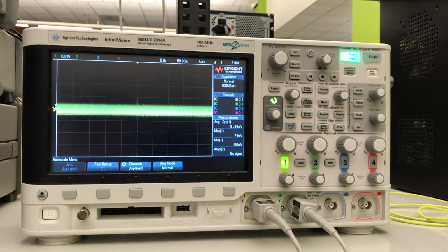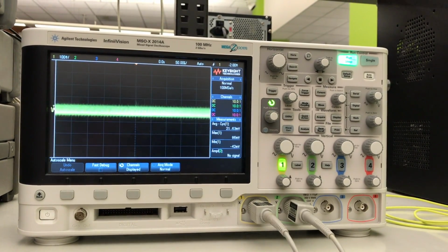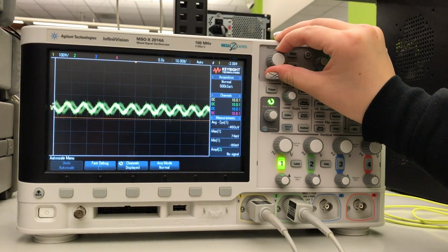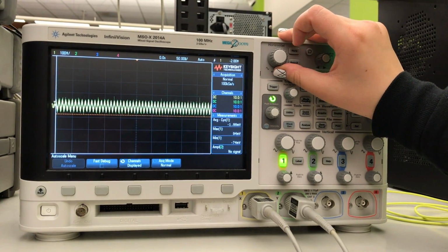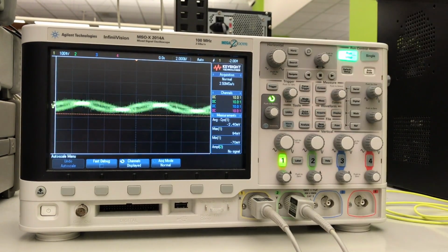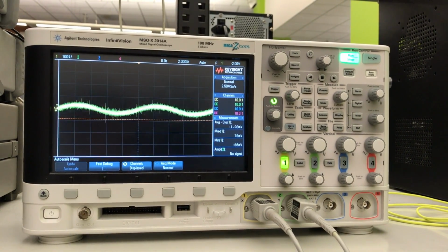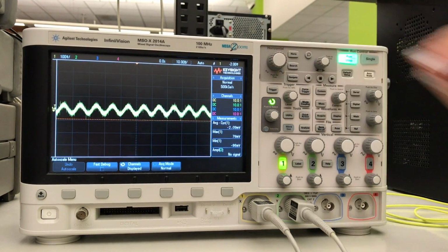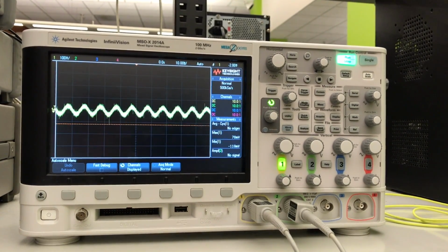Part of this is because we're looking way too close to the signal. We are far too zoomed in time. To adjust the time step per division, we use this knob here. So first I will turn counterclockwise to increase the amount of time per division. This is what the signal looks like at 50 milliseconds per division. And now we are at 2 milliseconds per division. As we can see, the signal is a little bit wiggly here, so we'll go ahead and increase to 10 milliseconds per division. Usually we want to try to fill the entire oscilloscope screen with our signal.